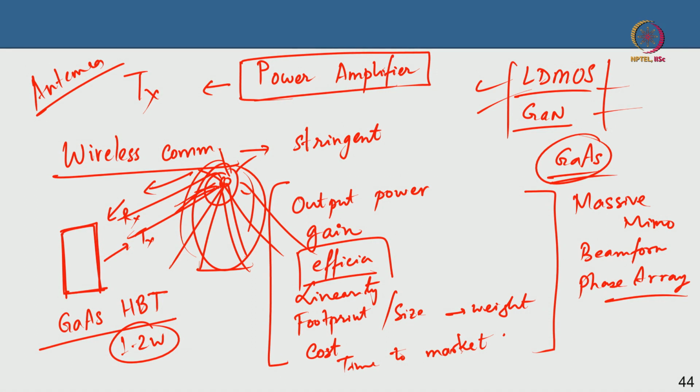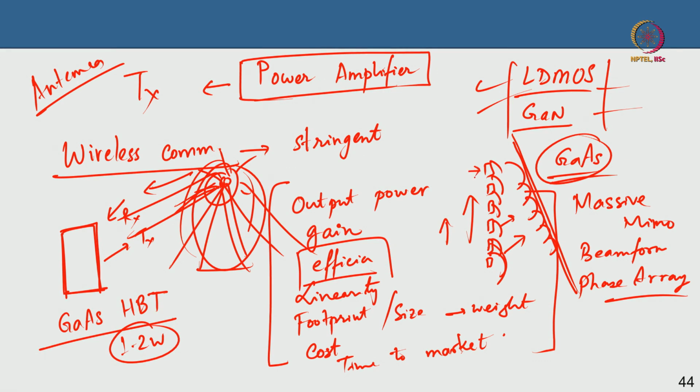You direct it to the desired direction and you do it electronically, kind of. You do not change the direction of the antenna, it remains constant, but by changing the phases of the signals, you have many antenna elements. These antenna elements emit the RF waveforms with a delay, so that every waveform looks like a constant waveform coming, but there is an increasing delay with a phase shift. You are introducing the delay among these different antenna elements, and each antenna element may be driven by an RF chip, could be an MMIC. There could be a power amplifier.